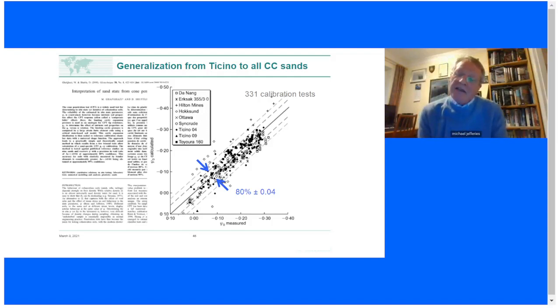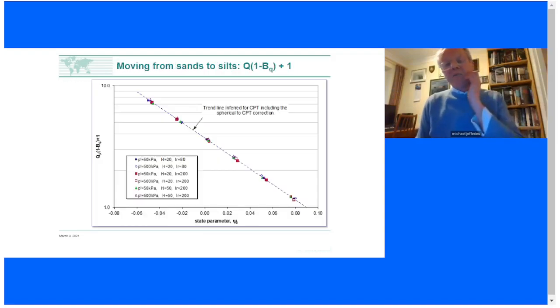If you then dig into it and say, well, is this as good as we've got? The answer is actually this diagram grossly overstates the variance. Bear in mind, these chamber tests involve placing 2 tons of sand carefully, and more to the point, accurately measuring the void ratio of that. Despite the CPT industry treating that as a gold standard, reality is a lot of experimental scatter. And virtually all the scatter you see on the plot here is actually down to the precision with which we can do calibration chamber testing. Now, so far I'm talking about sands.